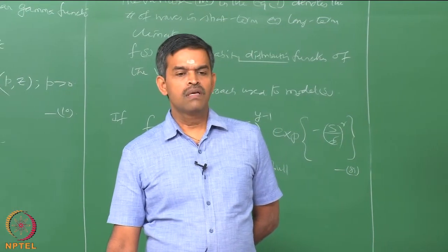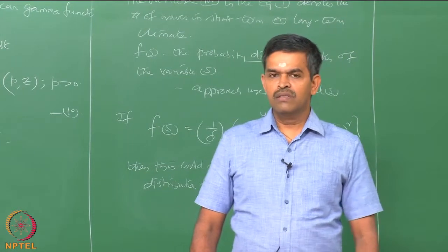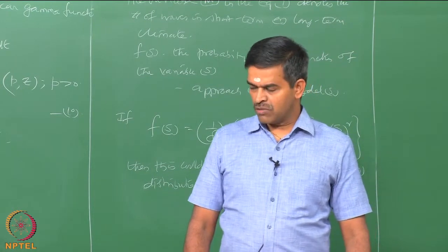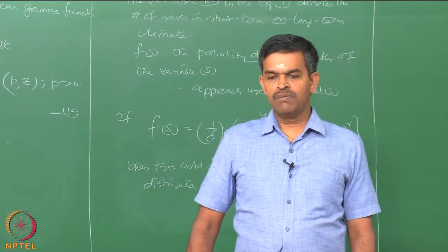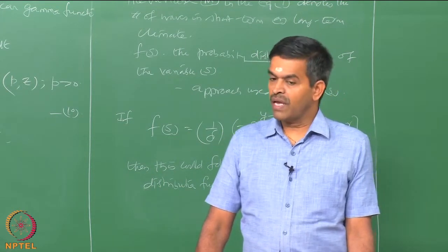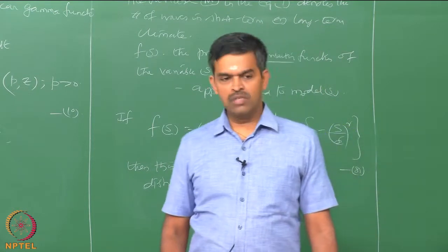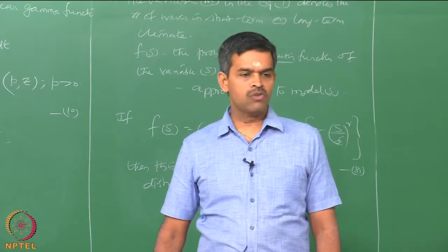So, friends, we are now going to discuss a very interesting problem where the tubular joints are actually loaded on an experimental setup, and the stress concentration factors are derived based upon the loads estimated using the sensors on the failure joints.